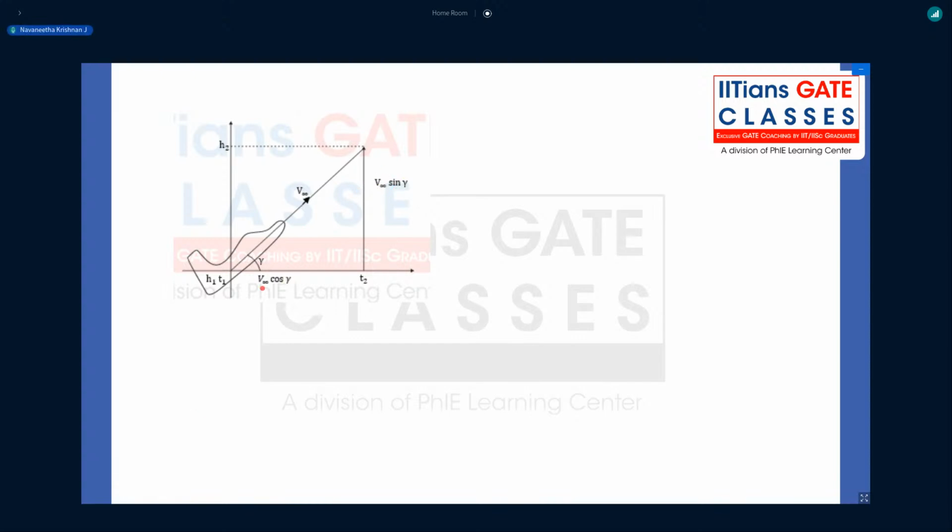This perpendicular component is called the rate of climb. V infinity sin gamma is called the rate of climb, and that rate of climb is the change of altitude with respect to time.